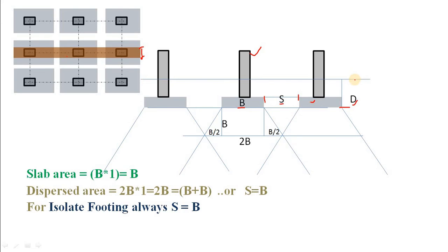What is the soil mechanics? When the load is coming to this column, it comes to the foundation or the footing slab and it disperses like this. What is the angle? Normally it is considered that for 2 unit vertical depth, the horizontal dispersion is only 1 unit.